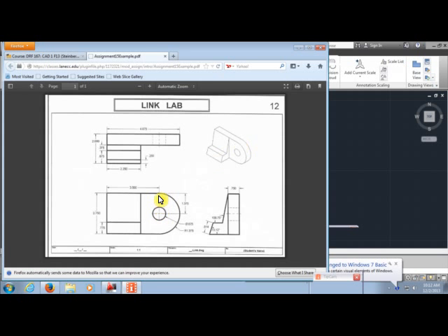So I look at this drawing here and I say, okay, I know that the distance from here to the center of that circle, which is also the center of this circle, and meaning that the point of tangency there is that same radius, is 3.5. And I know that this little block section here is 2.25, so I subtract that from my 3.5, and I figure out that this section is 0.75.